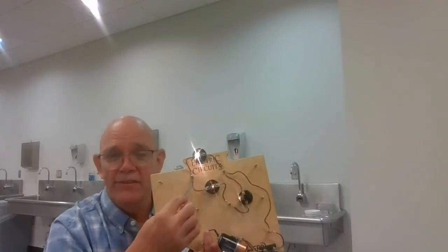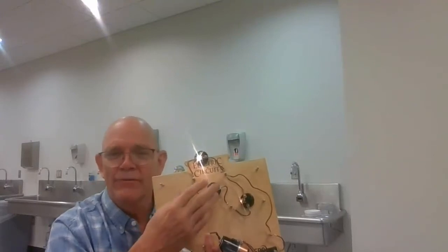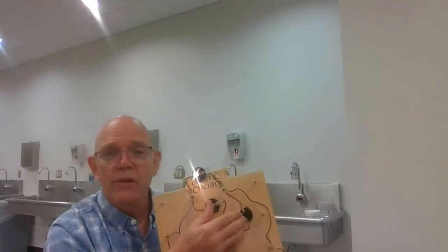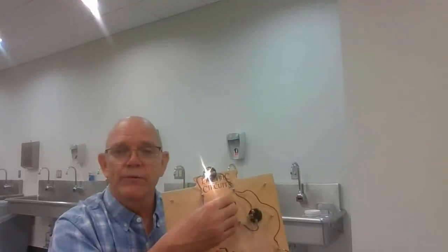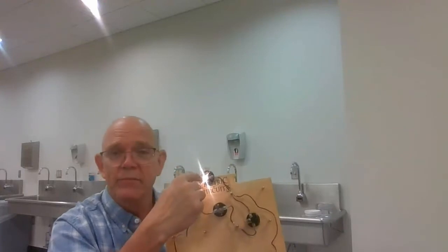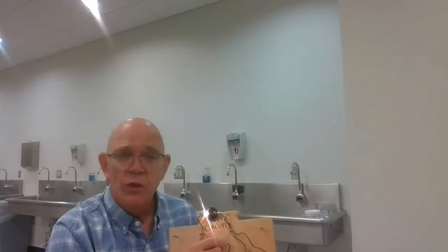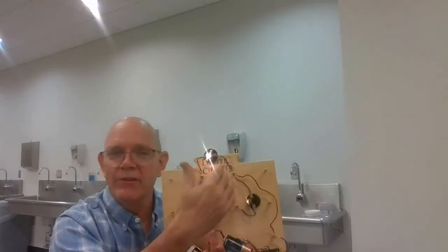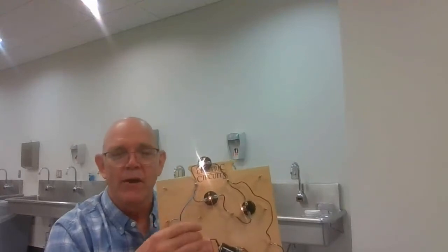And so even though this branch gets the same amount of voltage, you have double the resistance, and so you have less current going to these 2 light bulbs. And so these 2 light bulbs have less, and so that's why they're dim, kind of like a series circuit. Okay, if one of these goes out, guess what? The other one goes out, but it doesn't make the one up here go out. Okay, so anyhow, you can have a series on one of the branches of the parallel circuit. Keep in mind that each branch still gets full voltage, but you have more resistance now, so you have less current going through this one. All right. Okay. So anyhow, that's kind of what we want to see with that.